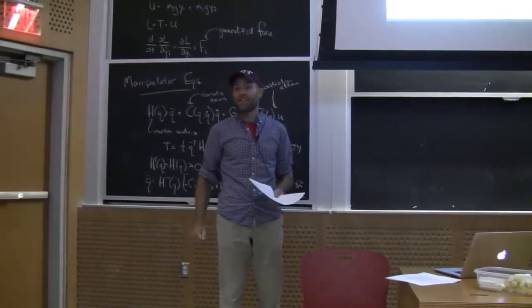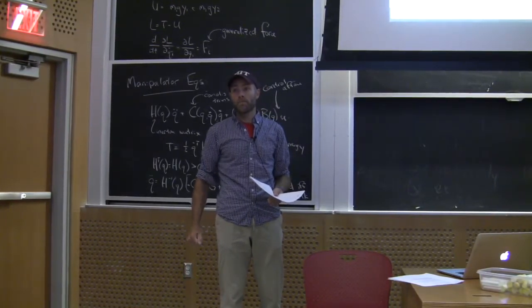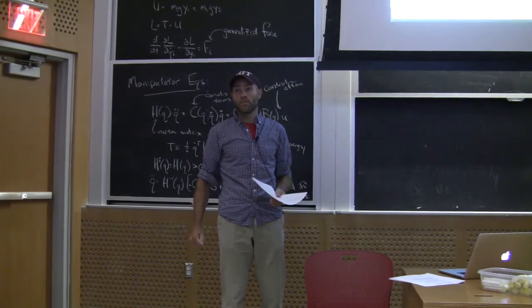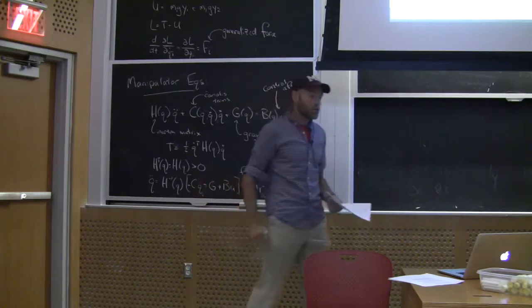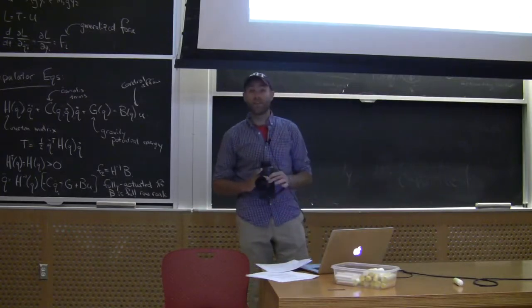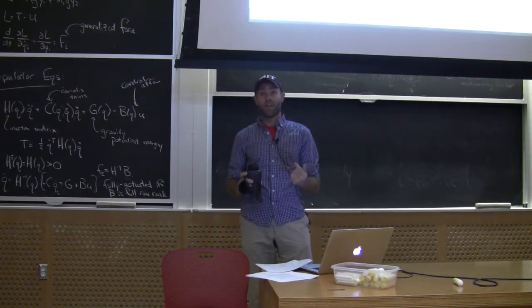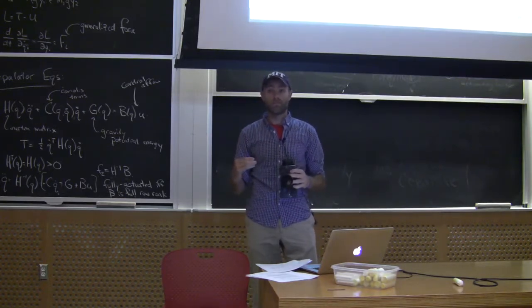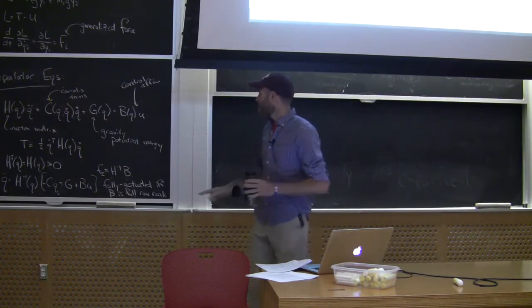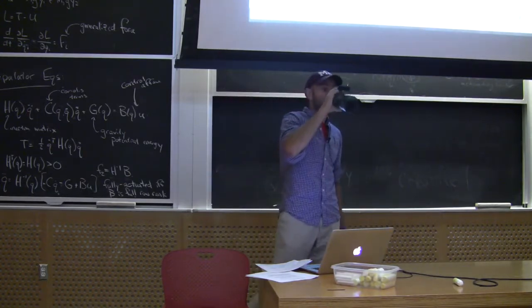Yeah? So you mentioned needing an actuator to fully control this at the other joint. Yep. But could you control it by moving first actuator and another? So that is the topic of the course. Having not enough actuators means you can't instantaneously accelerate in arbitrary directions. It doesn't mean that you're necessarily very impoverished as a control system. It just means that you have to be more clever. I can't make this system look like an arbitrary linear system and apply linear control techniques. I have to think about F, okay? I have to do more sophisticated control.